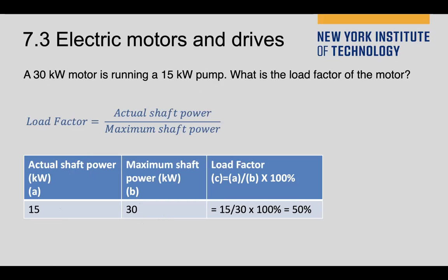Question number 3. In question number 3, it carry another concept is load factors. So what is load factors? By the definition of load factor, which is the actual shaft power over the maximum shaft power. So you need to know, even I have 1 horsepower motor, but sometimes when it operating, it may not draw the capacity of the motor, especially for the motor in a continuous one.